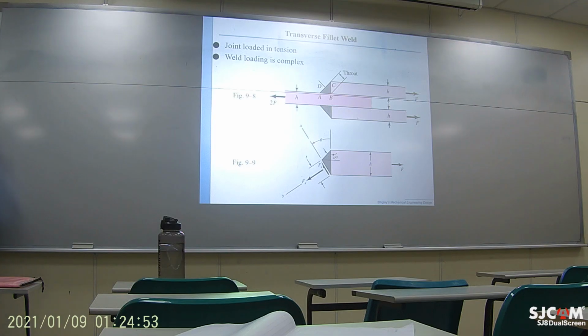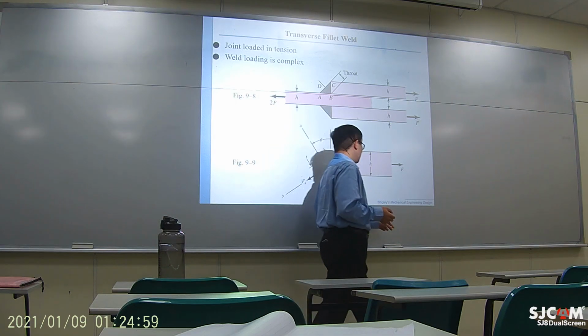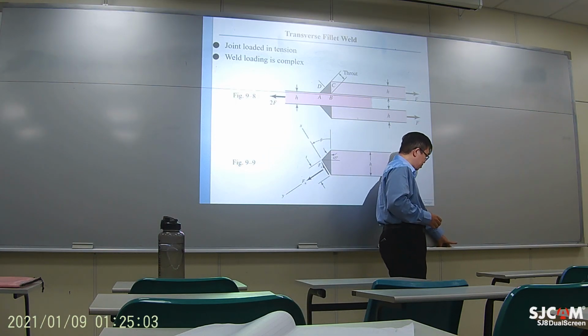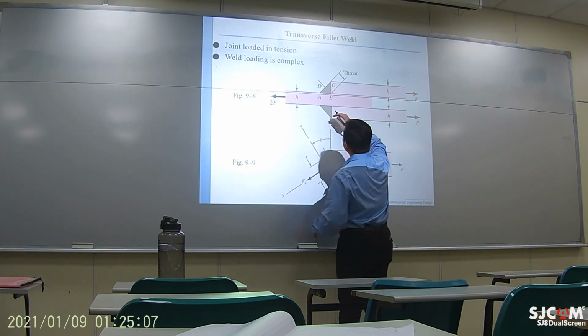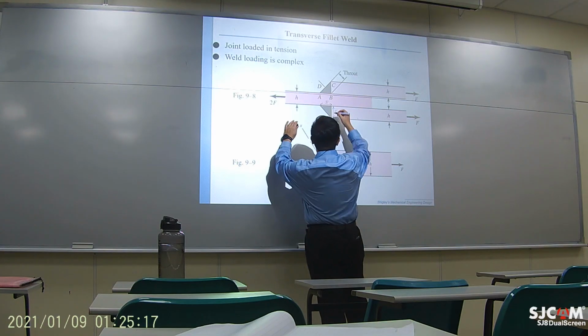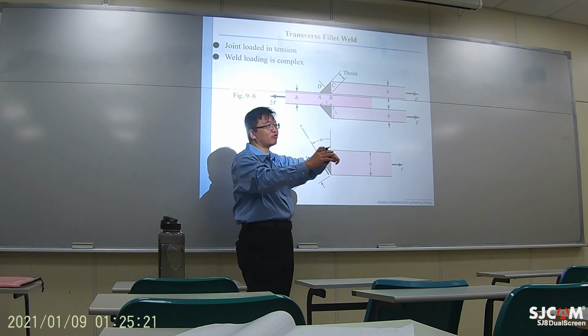If you do not know about this, sometimes when you do welding, maybe they ask you to weld this corner with certain dimension. Maybe it will tell you, okay, 5 here, 5 here. So when you study stress, you may just use 5 times L as your stress area.